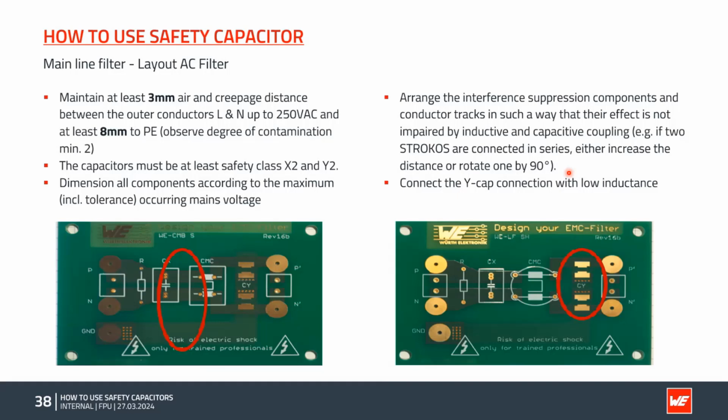So Frank, when you're mounting those Y caps, what do they look like? Because you showed examples that were through hole. Do you have a line of parts that are also surface mount, or what's going on down there? Yes, this is one special thing for us, because we have only SMD Y capacitors at the moment. We are working to bring THD Y capacitors as well. This is why the examples here are with the SMD types. You're right, this is different for my example.